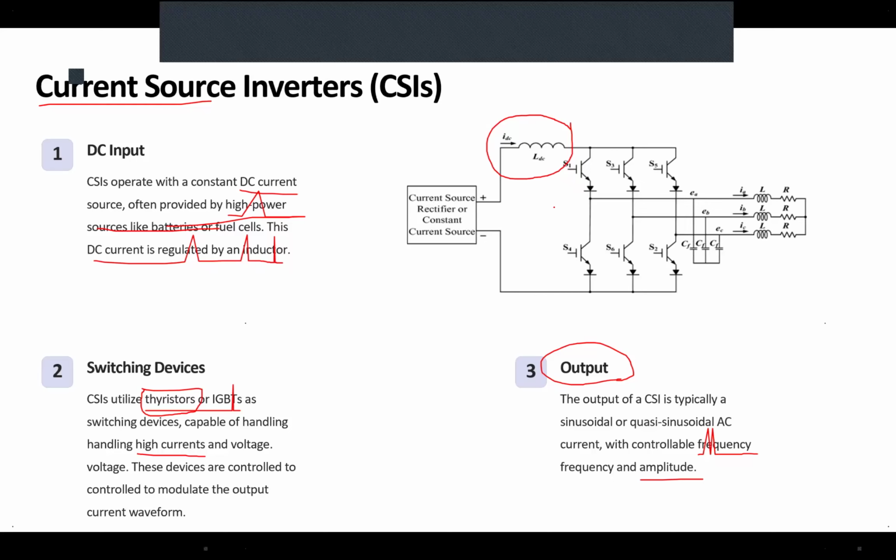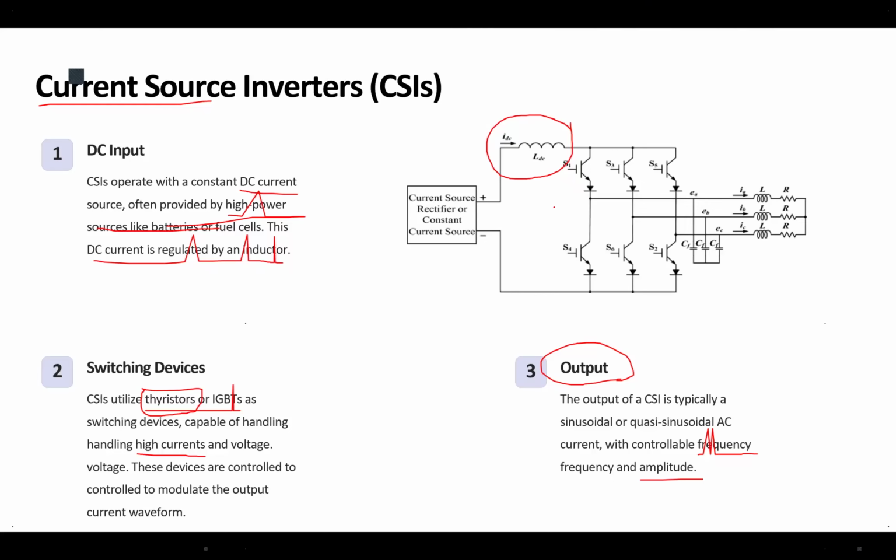The topology that you see on the screen is a three-phase inverter. It is a full bridge three-phase inverter. Each of the legs provides one of the phases. Besides the fact that they have to have a 120 degree phase shift with each other because it is three phase, to answer your question, no, the PWM is the same as what we discussed before. The technology in the control is the same as what we discussed before.